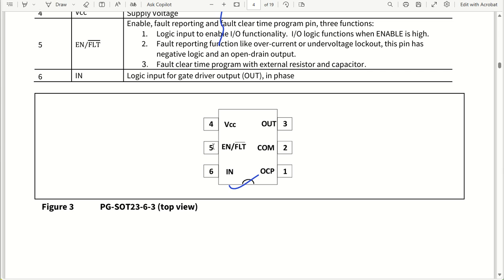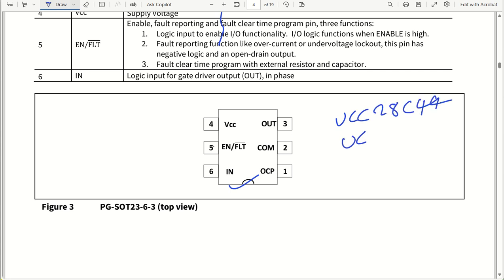So anyway, moving on from these things, what we'll do is we'll try to explain more complex ICs. Let us say we can explain UCC28C44 or UCC28C55. Okay, so these two ICs are in my mind, so that you can become very thorough in gate driver design, or flyback converter design, or all those kinds of PWM controller design. So these are all called PWM controllers.